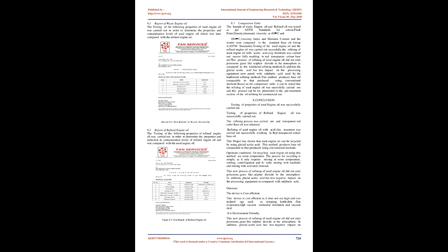8.3 Experiment 3. 10 ml of waste engine oil was taken and mixed with 1.2 ml acetic acid for 60 minutes and kept for 24 hours. After 24 hours, centrifugation was performed for 1 hour. Conclusion: the dark black oil turned out to be light black. Also, after centrifugation, the contaminants got settled at the bottom of the test tube. Figure 8.3, Experiment number 3.